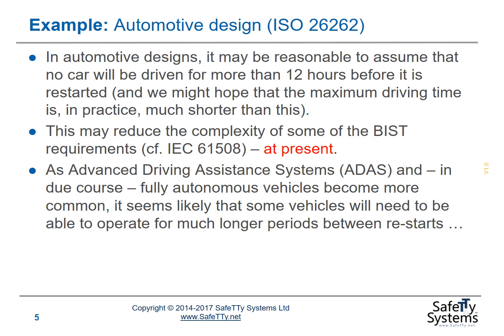Let's consider another example, an automotive design developed in compliance with ISO 26262. In current automotive designs, it may be reasonable to assume that no car will be driven for more than 12 hours before it is restarted, and we might hope that nobody drives for as long as 12 hours. Anyway, this may reduce the complexity of some of the built-in self-test requirements compared with IEC 61508 at the present time.